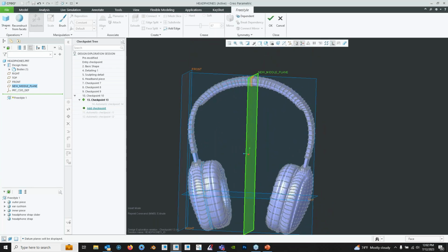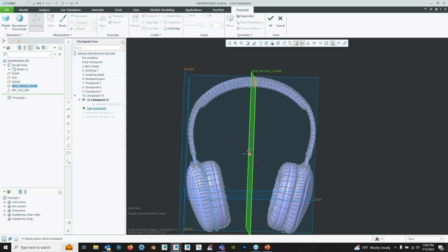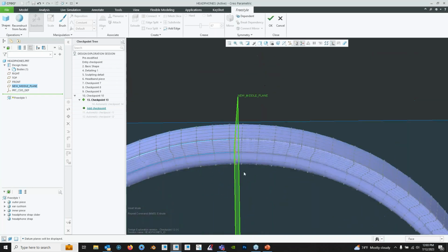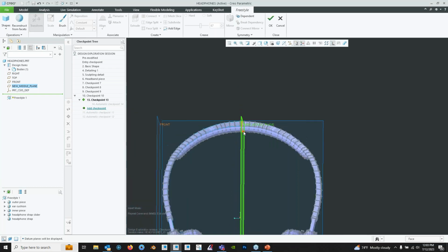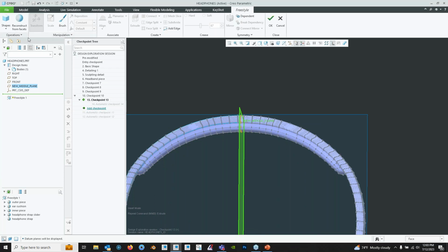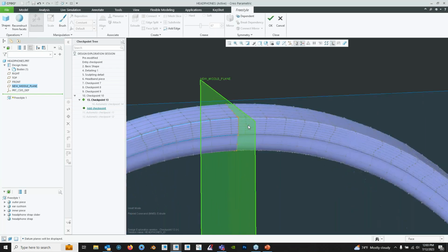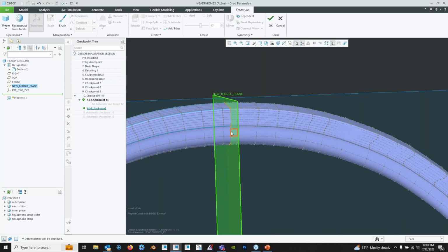Originally too, since headphones have sort of that bend inwards, because they have that flexibility to, you know, as we pull the headphones out and stretch them and put it on our head. Originally, I had to take all of these and rotate them inward like this, and I had to extrude these inner faces here to get aligned to this plane first. So there's an align tool that'll perfectly align the faces or the edge loop that you want perfectly straight to the plane.